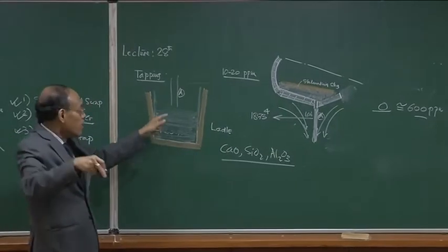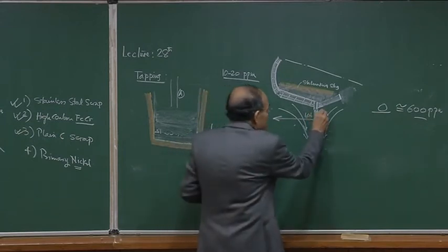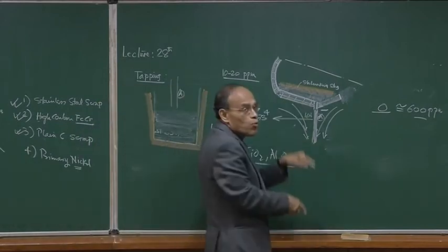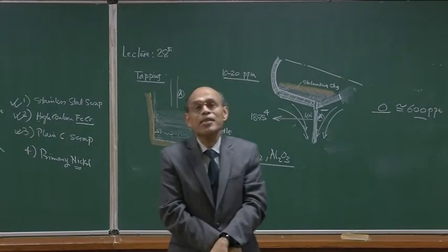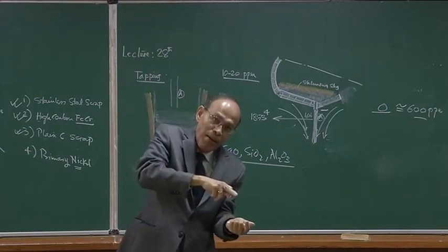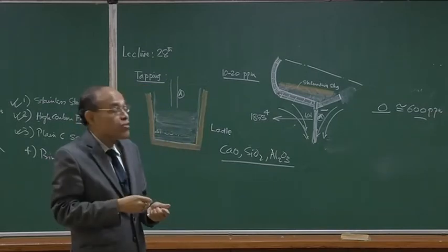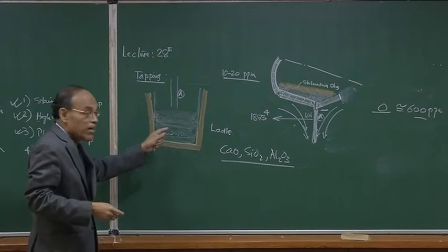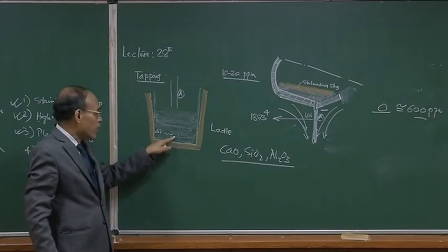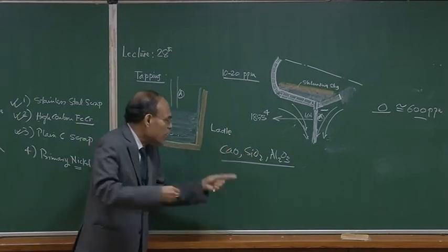And when the molten metal comes from the furnace, the kinetic energy could be very large because of the drop. The ladle itself could be 3 meters in depth, and the exposed length above the ladle top could be another 3 meters or 5 meters. That means the steel is falling from a height of 7 to 8 meters from the base of the ladle, with an enormous amount of kinetic energy, and as I said, 10 tons per minute is the rate. So, you can imagine the momentum that is going to be brought in here, and that momentum is going to create a huge amount of churning action in the ladle itself, expediting the melting, dissolution and reaction of all those elements we have added.